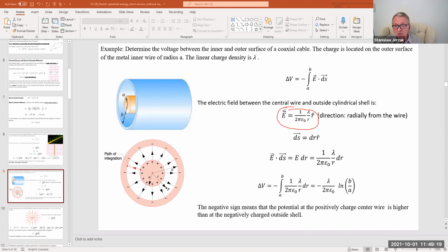This is the electric field. So electric field is the same, it goes radially, right, between inner wire and outer shell. And I want to now calculate what is the potential difference, what is the voltage between that inner wire and the outer shell. So I want to integrate to find that voltage or potential difference. Potential difference is a proper term between these 2 points. This is maybe point A on the surface of the wire and point B on that inner surface of that shell. I want to integrate that electric field from that point A to B. So I want to evaluate that integral.